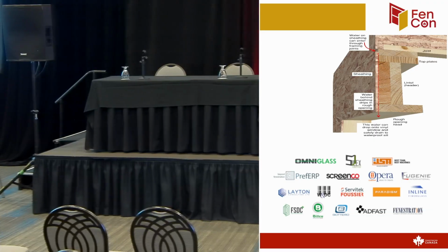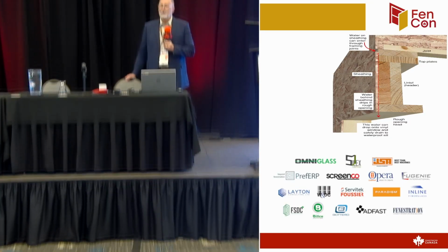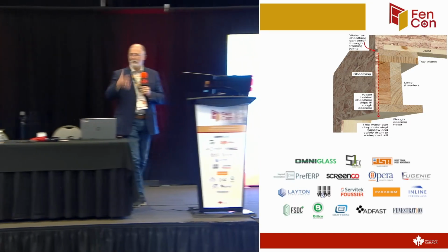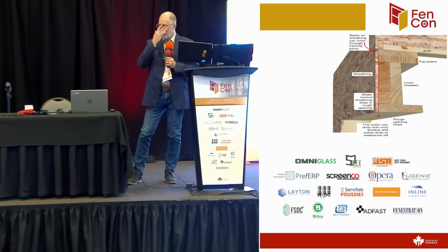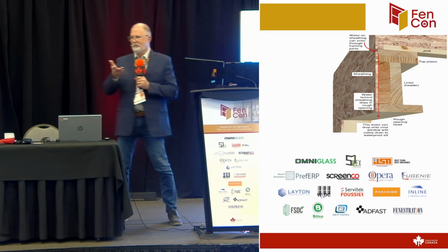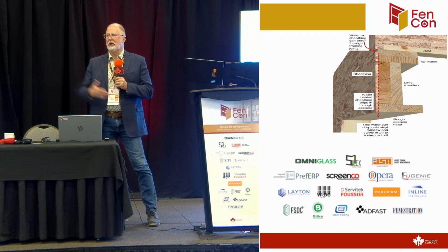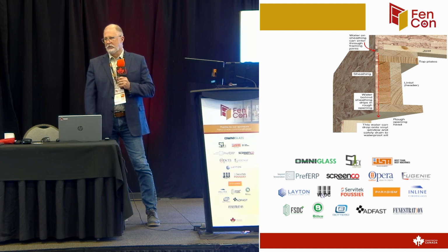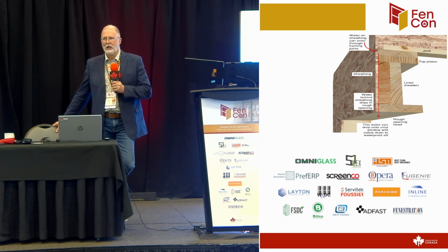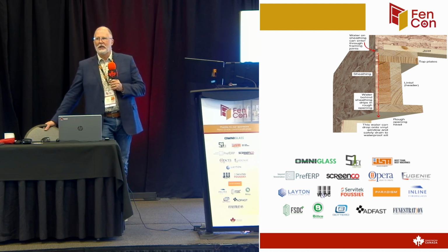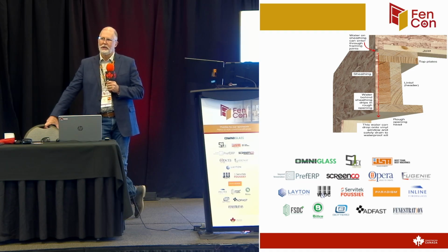If you're doing EIFS, EIFS used to be problematic, but nowadays it has built-in drainage. You have the geometrically carved out EPS foam that goes up against the vertical grooved adhesive, but I can't think of any cladding that you wouldn't have drainage behind. Nice. Yeah, no problem.